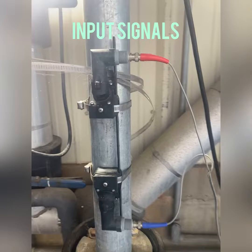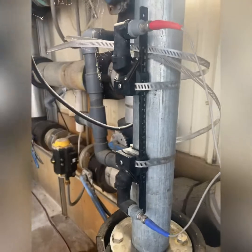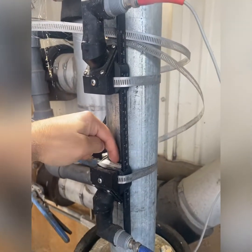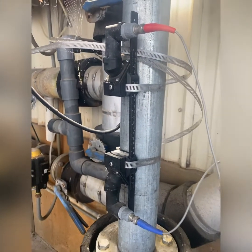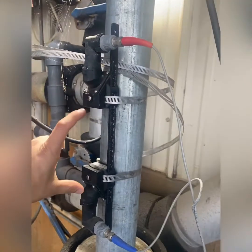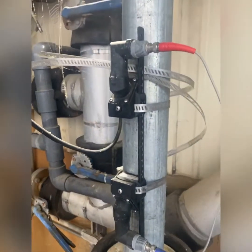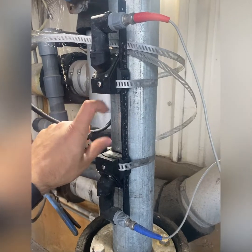As I showed you in the settings, this is carbon steel, and here's the way you put these bolts together. You have to make sure that you use the gel underneath. There's a gel that comes with the unit, but you can always find the right gel for your application. If you don't use it, you're not going to get a good signal right here. The distance all comes in the manual, so you can go back and check it. It depends on the pipe size and your application, whether it's water, oil, or something else. Based on that, you can adjust the distance.